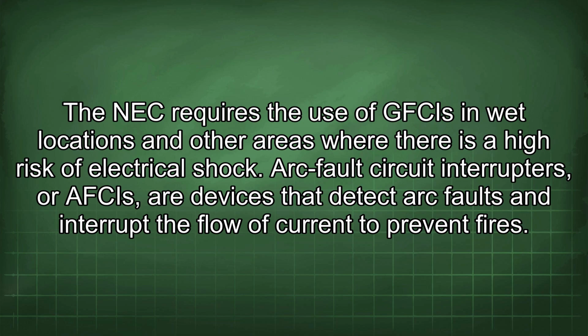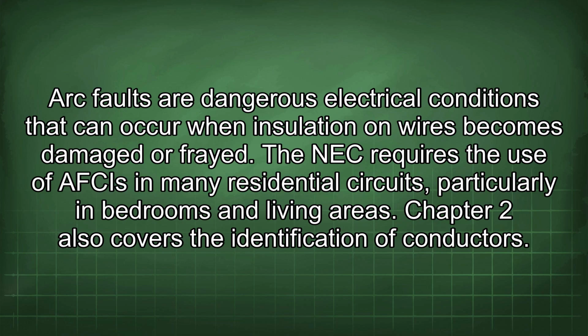electrical shock. Arc fault circuit interrupters, or AFCIs, are devices that detect arc faults and interrupt the flow of current to prevent fires. Arc faults are dangerous electrical conditions that can occur when insulation on wires becomes damaged or frayed. The NEC requires the use of AFCIs in many residential circuits, particularly in bedrooms and living areas.